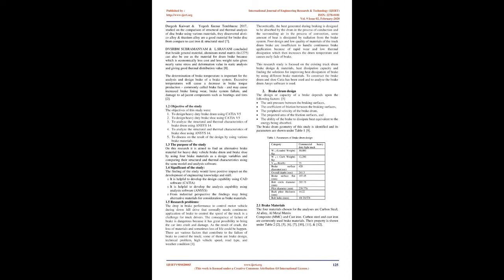Post-processing is used to create graphical displays that show the distribution of stresses, strains, deformations, temperatures, and other aspects of the model. Interpretation of these post-processed results is the key to identifying areas of potential concern, weak areas in a model, areas of material waste, areas of the model bearing little or no load, or valuable information on other model performance characteristics, thermal, modal, that otherwise would not be known until a physical prototype were built and tested.